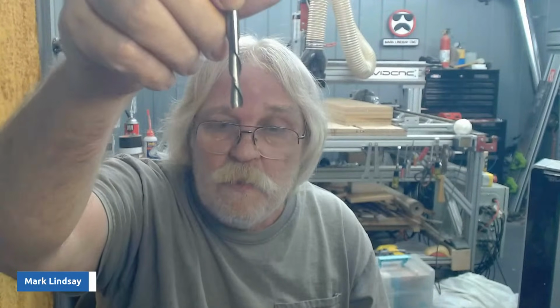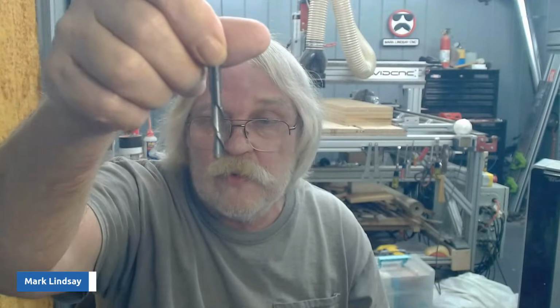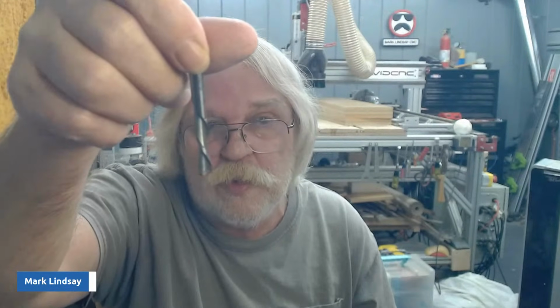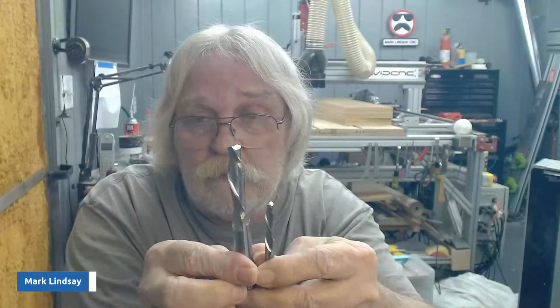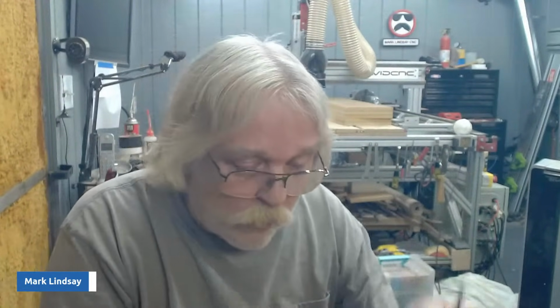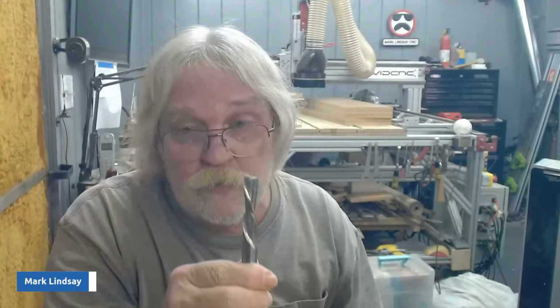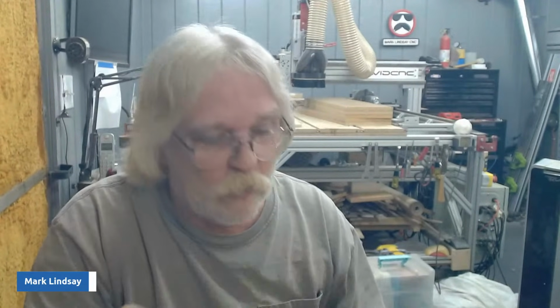This is a 1/2 inch down cut end mill. This, I wouldn't need to use a thin first pass. I could just split it up into 2, 3 passes, 4 passes, depending upon what the material is. If it's really hard stuff, this is a 1/2 inch end mill. So if I'm really cheesed off at the material, I'll switch up from this to this. Guess who's going to win? The CNC router is going to win. We all know the answer to that. But this sucker will move some material, I'm here to tell you what. It'll sling stuff everywhere.